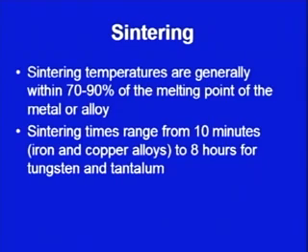Sintering times range from 10 minutes, for typical examples like iron and copper alloys, which require 10 minutes of sintering, up to 8 hours for tungsten and tantalum. So, tungsten and tantalum require 8 hours of sintering, whereas iron and copper require only 10 minutes.